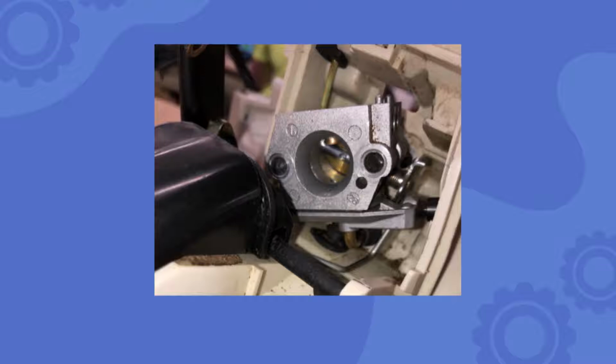Air gets sucked into the Venturi, which speeds it up and causes its pressure to drop. This drop creates suction on the fuel pipe, drawing in fuel from the reservoir. When the throttle opens, air and fuel travel through the carburetor and into the piston inlet.